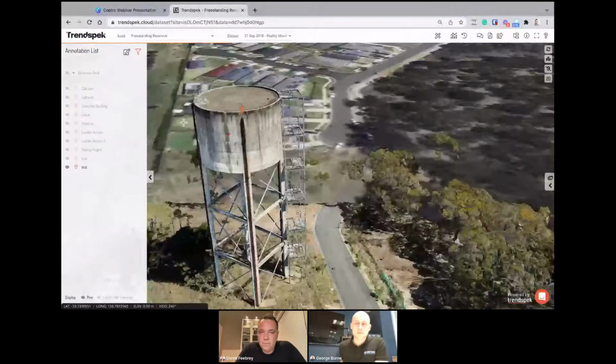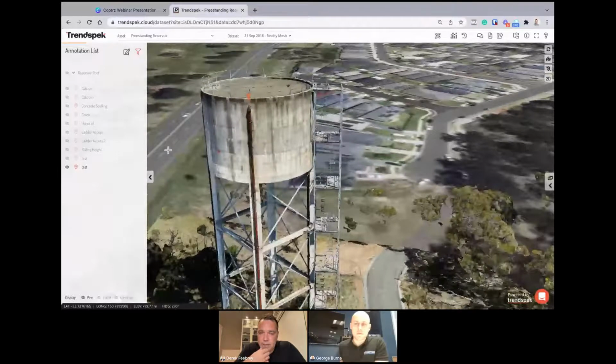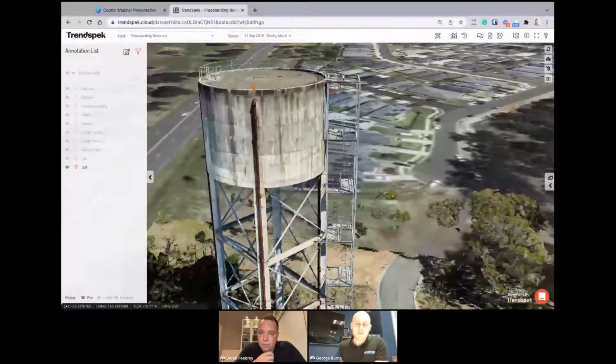So one of our best tips, to extend on that, is using an RTK drone, like an M300 RTK, which will give you really good GPS positions and enhance the model. Naturally, we don't have that internally, so it's a lot harder to do internals. But saying that, we do have a lot of internals. We have tighter spaces, such as internal bridge spans, where they've done it on their belly on a skateboard going through, capturing enough photos. So it can be done.